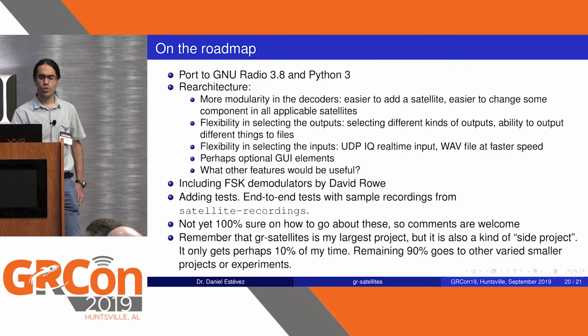I also would like to try adding some FSK demodulators by David Rowe. These work on the IQ signal rather than on the FM demodulated signal, and by doing so can achieve better performance by filtering the different side lobes of the FSK signal.